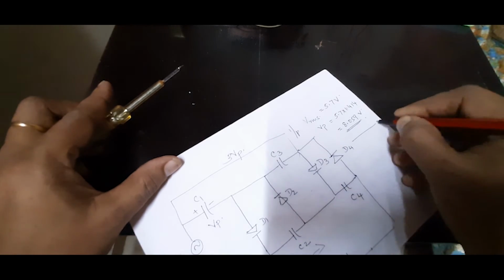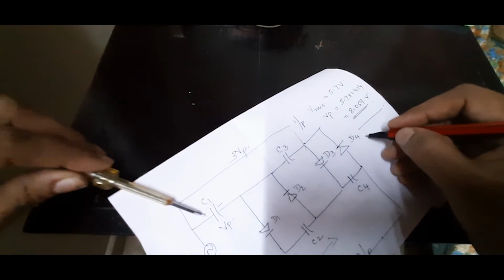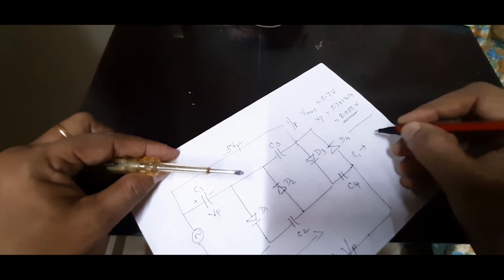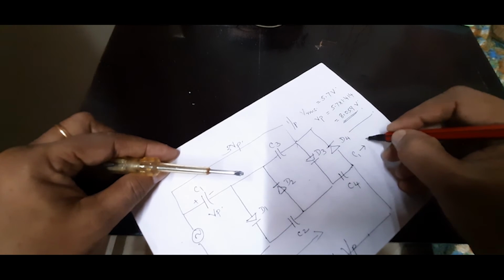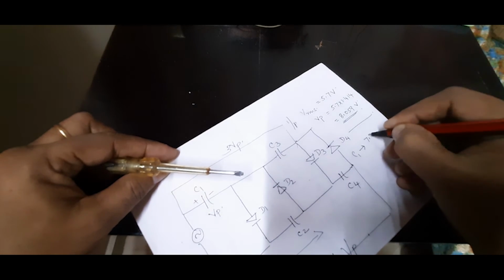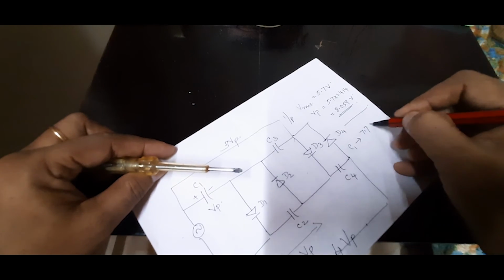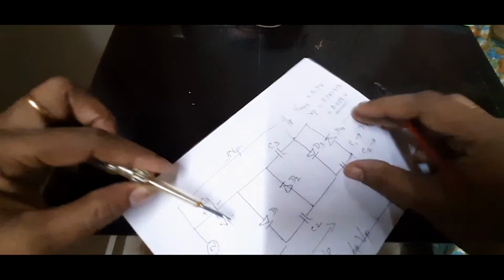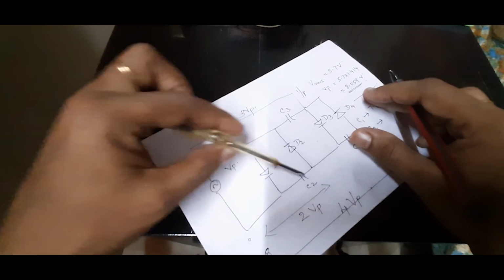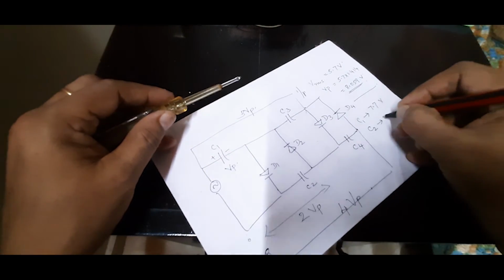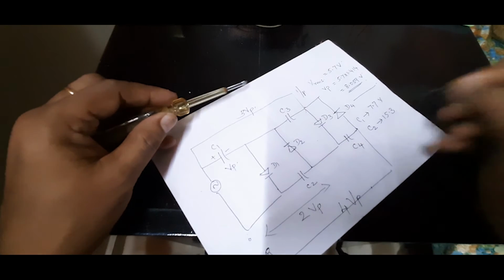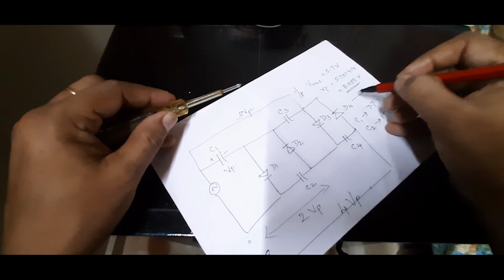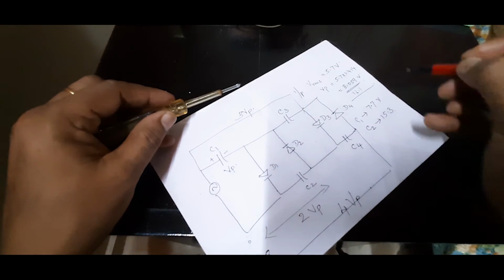This is regarding the input, and regarding the output that we measured across the C1 capacitor, it was 7.7, slightly less than the expected. That will happen. C2, that is the voltage that we measured across these points. If you had noted down, it was 15.3, and that should be double of this. Double of this will come to 16.1.